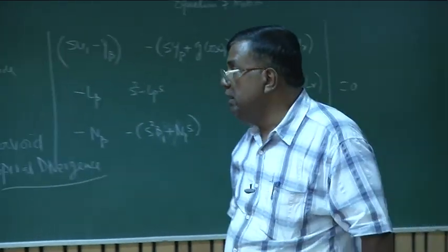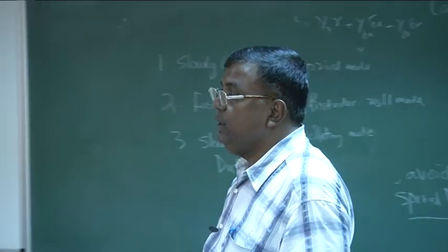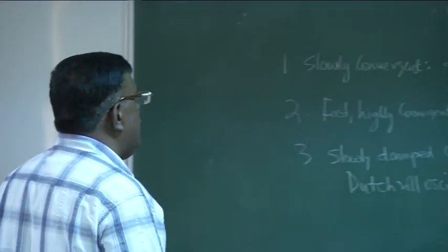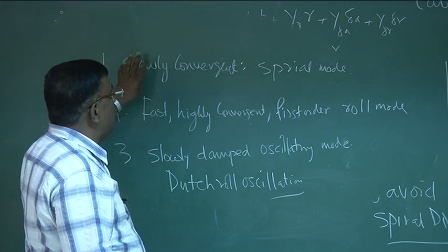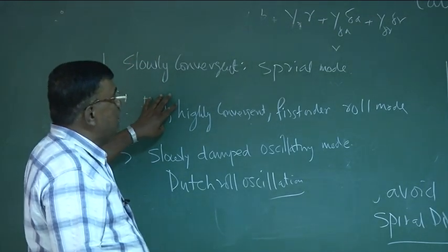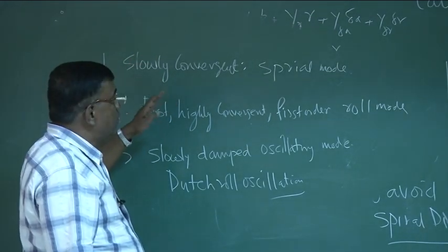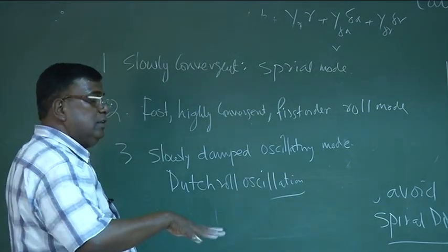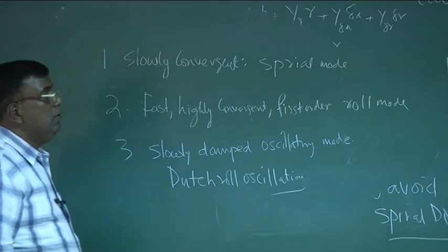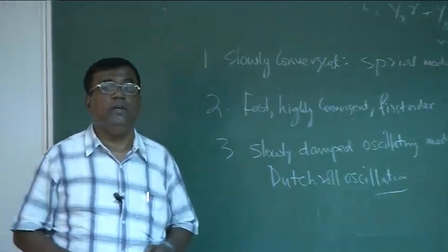So the airplane in the lateral directional case can get excited primarily in either of these modes or a combination of these modes, right? And that is why a designer needs to know the natural frequency, the time period, time to double, time to half. Similarly here, how much time it takes to go from one bank angle to another, and what is the oscillation natural frequency of the lateral mode, to design the handling qualities of an airplane.